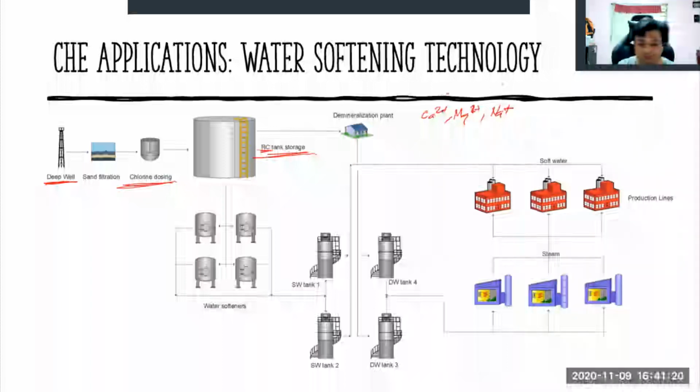If you remove these ions, the water becomes an insulator, a pure water, because you have removed these electrolytes. It will not conduct electricity anymore. Then it will be stored in the demineralized water, or DW, tanks, and then it is used as water in our boilers. So the water that is used in our boilers is demineralized water.